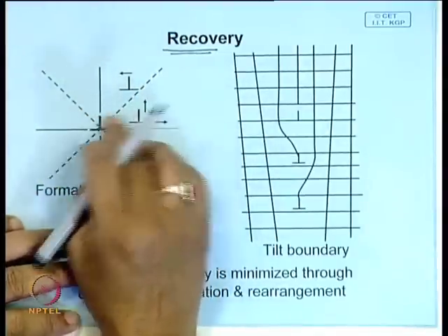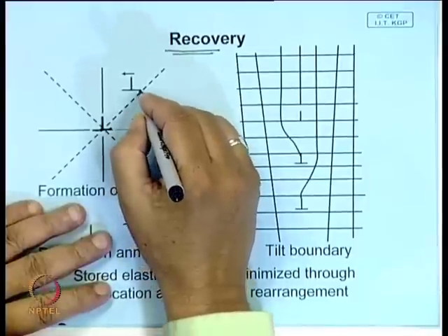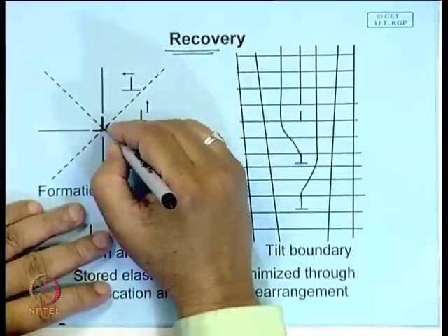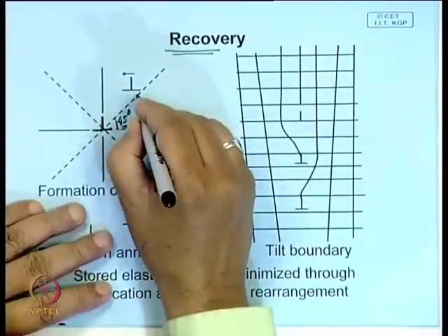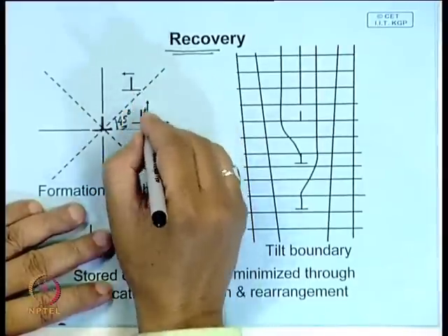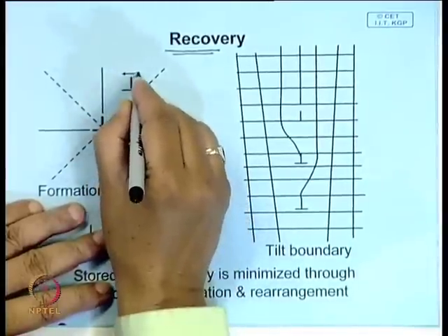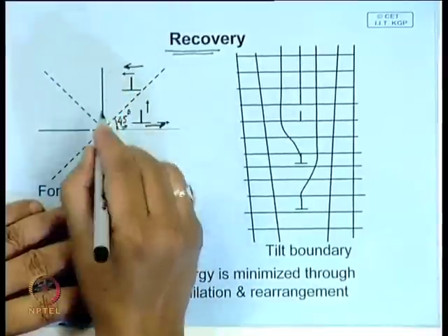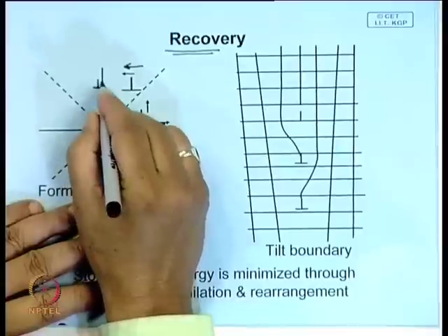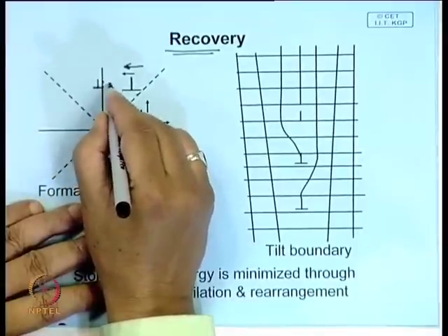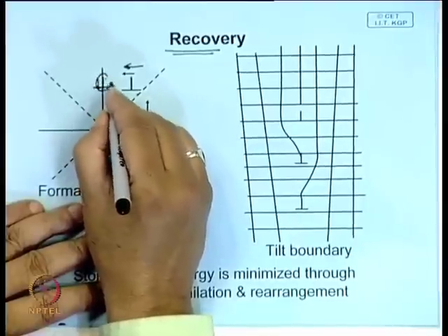So, it will be difficult to accommodate; the two will repel each other, but what happens if it climbs up? We have seen that this is a 45-degree line. If it goes beyond this, then the force on the dislocation, instead of being one of repulsion, becomes one of attraction, and it comes here. Once it reaches this particular point just above this, this is a stable configuration.